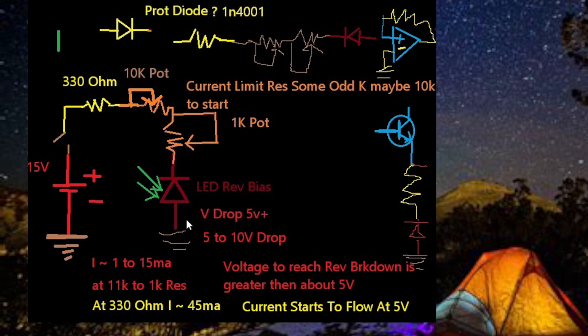And so we don't exactly know what the avalanche breakdown voltage is, or exactly even how to measure that. If we can't measure the current directly, we have to measure it indirectly by measuring the voltage across the 2 megohm resistor, and every time we change that, we get a voltage drop, and we can check, shut the circuit off, and make a chart and find out what that information is.